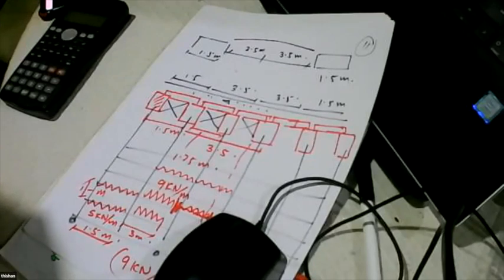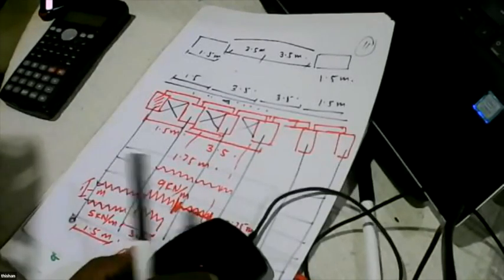And when you go with high strength concrete using fly ash, these reactions occur over a long period of time, and you end up with a really tough concrete section. When the concrete is tough, the steel will be properly protected, so you can easily reach 80 to 100 years or even more durability. So that is the position, and time is almost up.